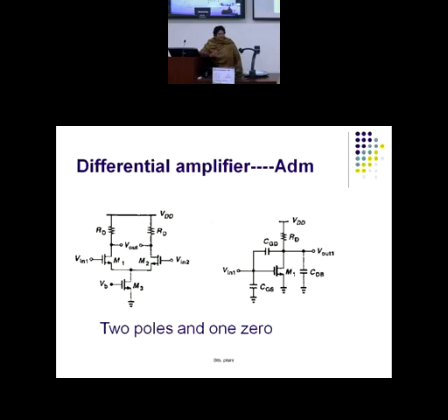And the gain will be half, GM RO by 2. We all know that if you tap only 1 arm, the gain will be half. So it is GM RO by 2 and then the zero expression divided by the 2 poles expression. Can you visualize it in your mind? You can. Now, visualize the same thing for VO2 with respect to Vin. Again it will be GM RO by 2 and then a zero expression divided by 2 pole expression.